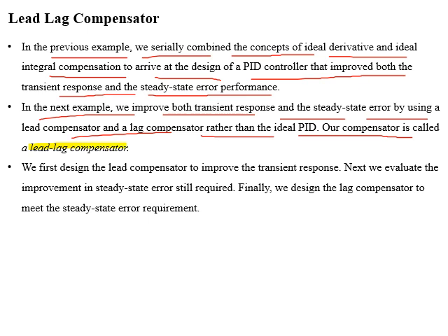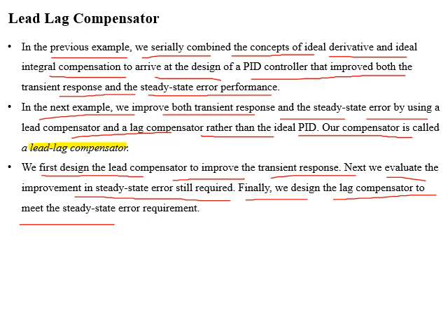We will first design a lead compensator to improve the transient response. Next, we will evaluate the improvement in steady state error still required, and then we will finally design a lag compensator to meet the steady state error requirements.